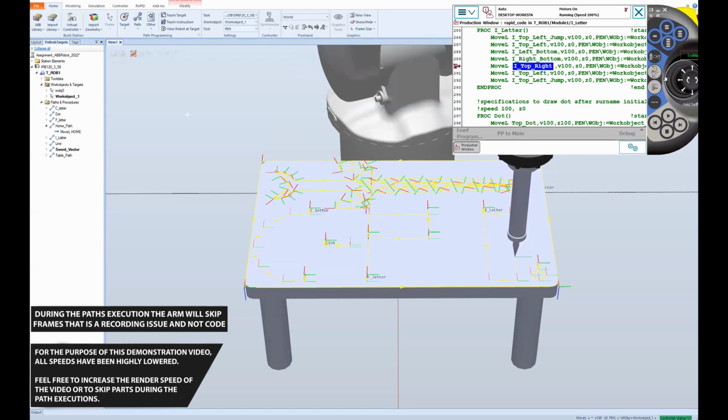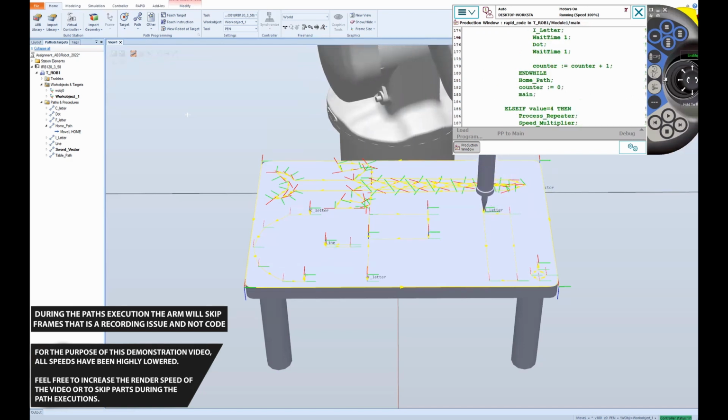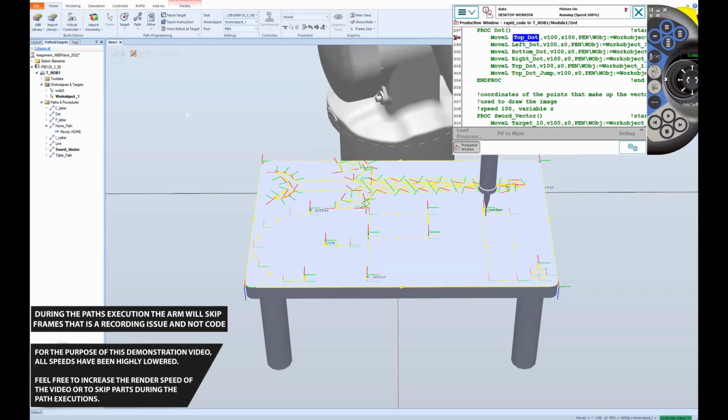Now, speed refresh is a very important function because again, in a factory environment, in the real world scenario, we can easily swap out the input from the user with an actual sensor, an ultrasonic sensor or an infrared sensor, or even a camera with computer vision, which measures the distance between the robot arm itself, the system, and either humans or users and objects around the system, which will then reduce the speed of the system proportionally to the distance between the user and the system.